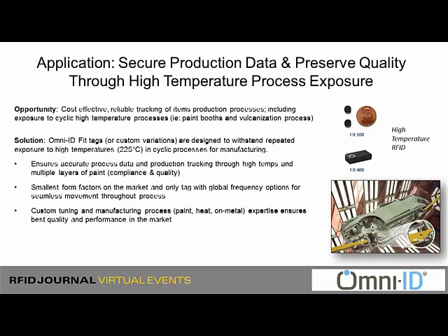These high heat tags can be covered over, they can survive overspray, they can survive pretty difficult environments in terms of shock and vibe. So if you were thinking before that you couldn't actually put some kind of label because you're used to thinking of RFID as a paper-based label, don't think that way. RFIDs have come a long way past paper labels, and you can certainly put high heat tags now in almost any application that you'd like, whether it's a high heat label or whether it's a high heat ceramic wafer or tag, as we show here. And we've done a lot of those applications already.